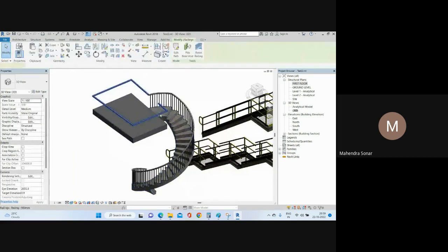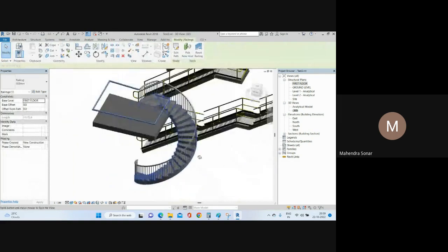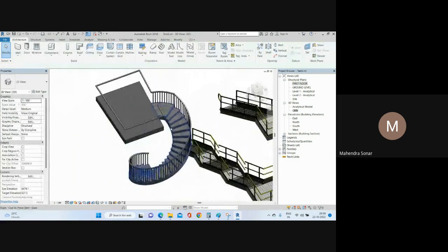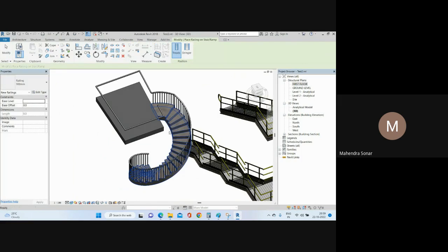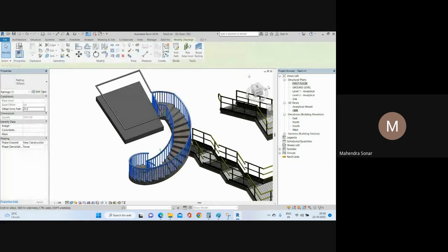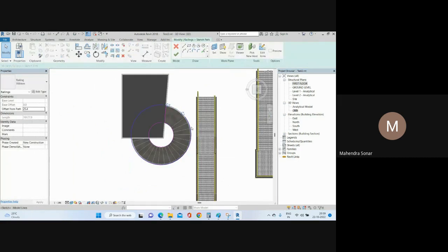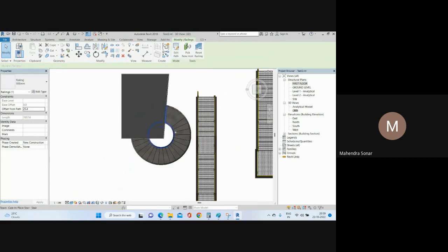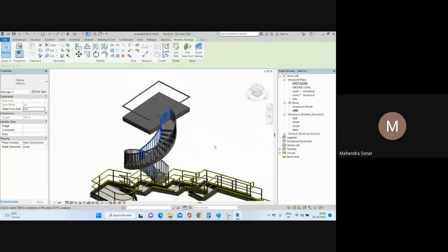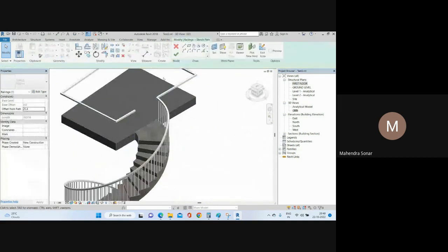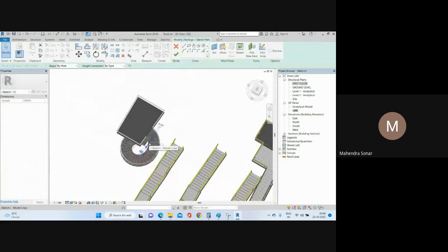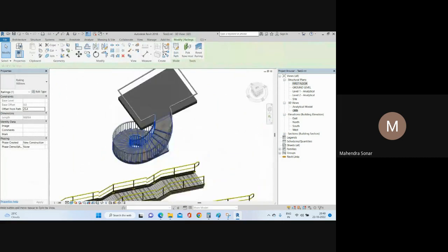This railing has, I think, some issue. So yeah, we need to add the inner side of this railing also. I will save first and go to the railing, use this option and add the railing, right? This time I will delete the outer side railing. So select Edit Path, delete outer side railing, and click OK, like that. I have deleted this railing also, and complete, like that.